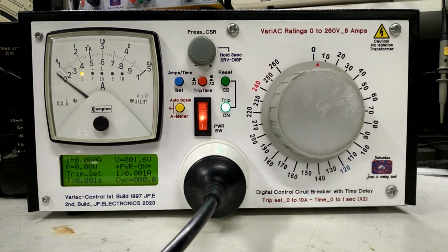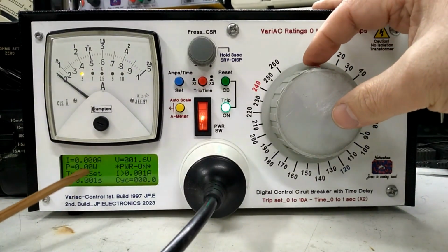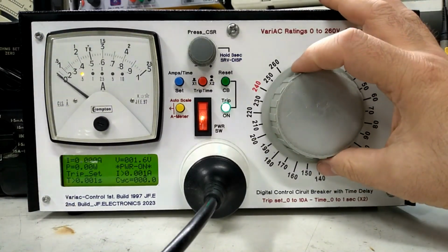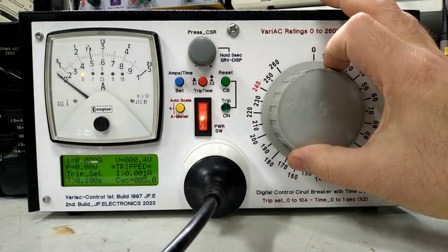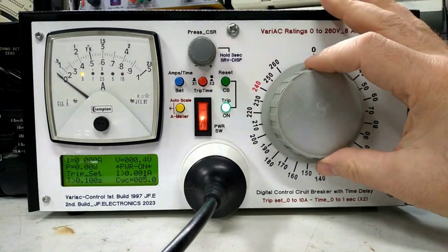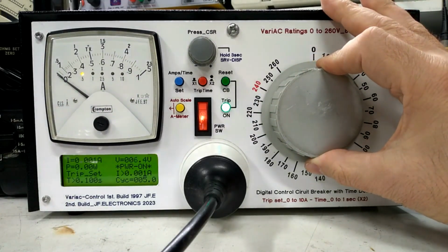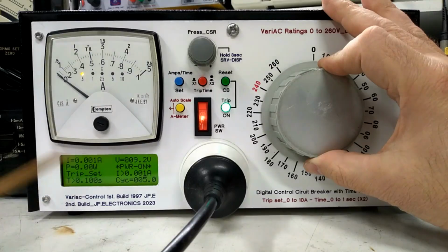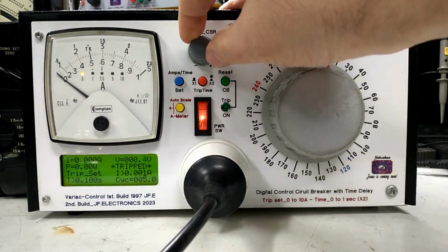So once I turn the voltage, and there's the current reading at the top left, it should trip around the 1 milliamp. Okay, so well, there you go. Maybe I turned it too quick. Redo it. So I'm putting up the voltage slowly. So it's reading 1. If I go a bit more, tripped. Now let's set it to 2 milliamps.